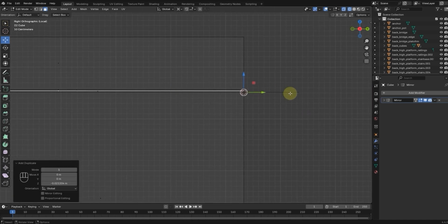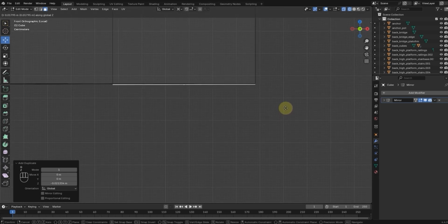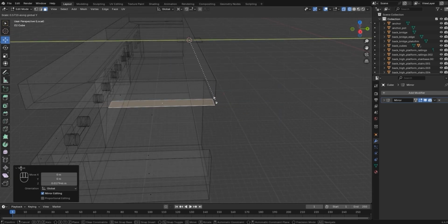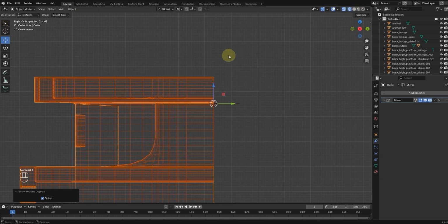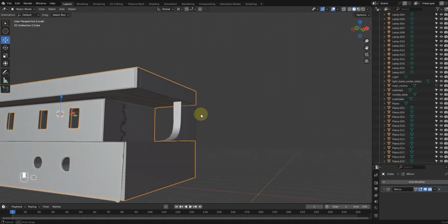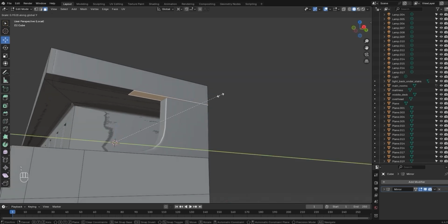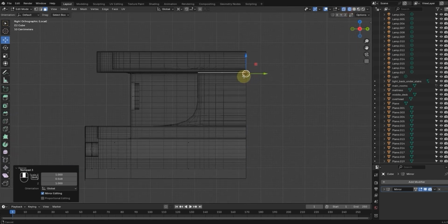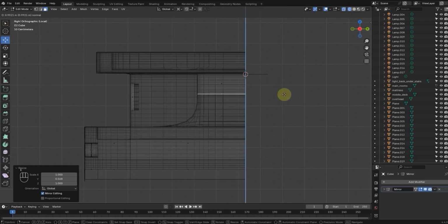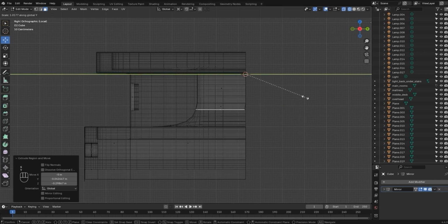You have to create a side joint. So what I'll do is duplicate that layer and reduce the size, pull it backwards, and then see if I can generate this curved part of the building. So I'm going to reduce that face backwards, and then I'll probably duplicate or extrude it downwards and expand it, increase the length on the y-axis towards the front.